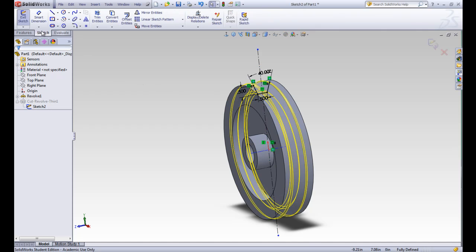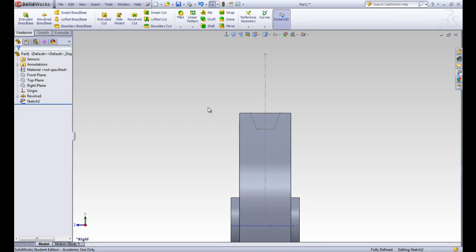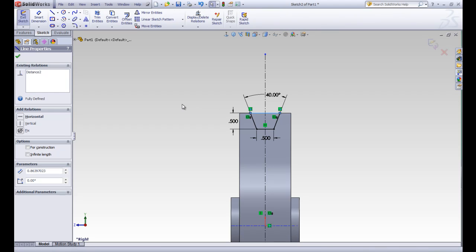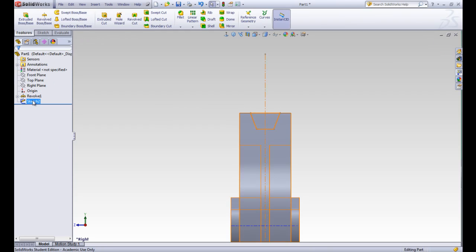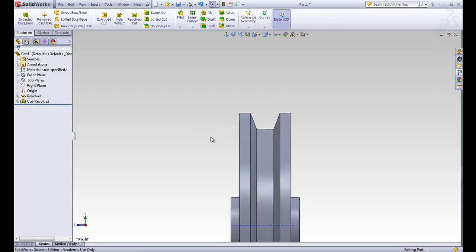So let's go ahead and hit undo again. Remember that the undo button is good to try different things on your own. You can always undo what you did and get it back to how it was before. Okay, so we'll go ahead and exit the sketch and revolve this the right way. Replace that line one more time and accept it. Alright, so that's how we want it.